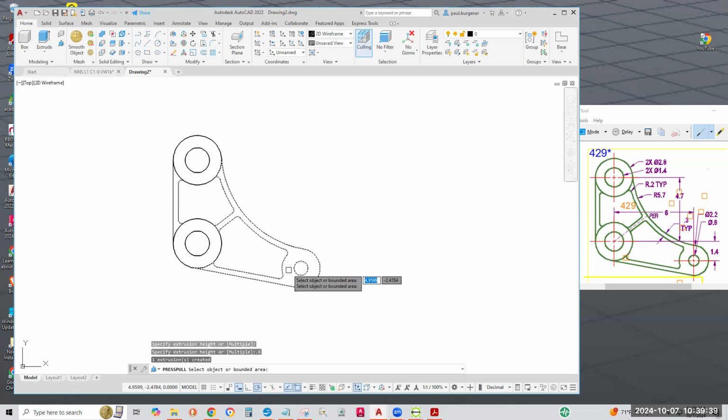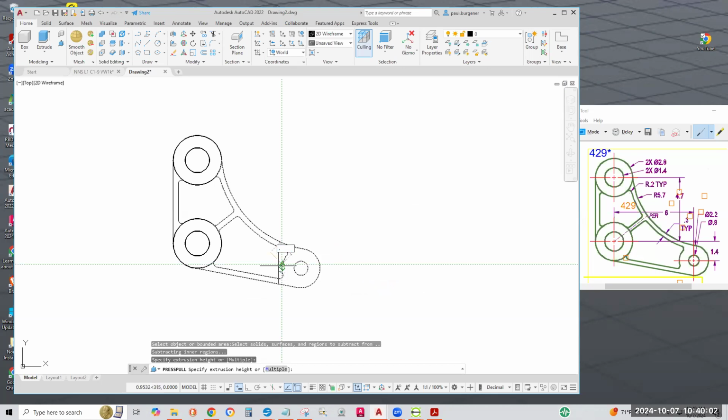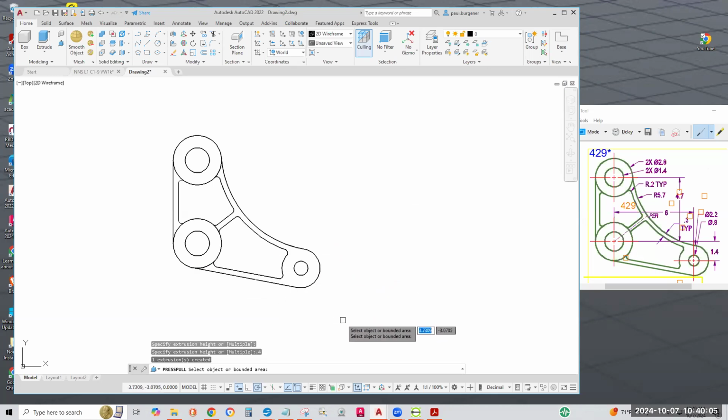Enter. And those are the big objects, so leave it as it is. Hit enter to finish. Enter to press pull. Click between the objects. Now hope this will work. You've got to have perfectly closed ends. So let's see if I drew it perfectly. Click. Extrusion height would be 0.4. Medium size extrusions. And we'll click there. Extrusion would be 0.2, enter. Click there, 0.2, enter. Well, let's see if it worked.